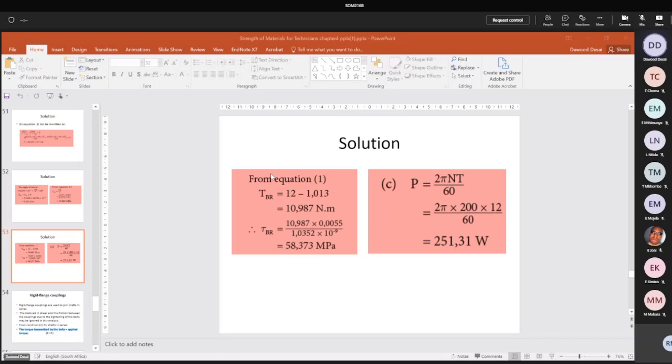Tire of your motor car, of your bike, can also be classified as a pressure vessel. It's holding fluid, which is pressurized air or nitrogen if you're into drag racing, you know. Also, many examples, right? Longitudinal, you got two types of stresses that are formed. Normally three, but we only concentrate on two. So any pressure vessel is subjected to two main stresses.